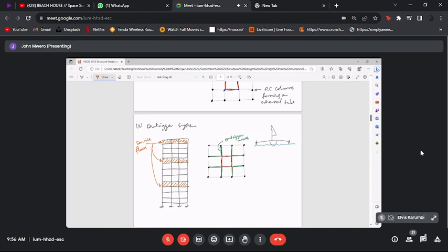So the water will be pumped up in stages. It is the same thing with the wastewater. If you allowed wastewater to just flow from the top of such a tall building to the bottom, then you'll have a problem with your fittings because they will just break. The pressure in the pipes would be so immense that you will not be able to get taps that are able to hold the pressure in the first place.